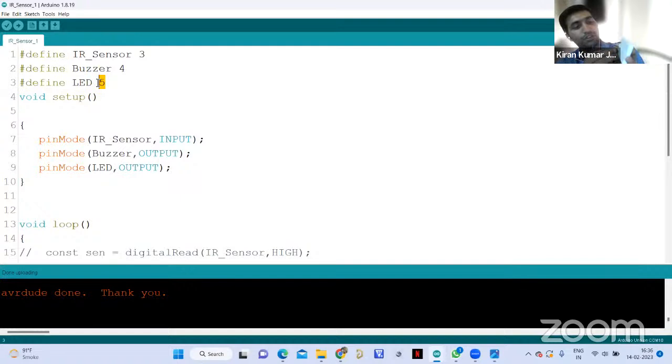Connection is quite simple. I have taken the IR sensor's output pin to pin number 3. So I have connected pin number 3 over here, the digital pin of the Arduino Uno. The rest is quite simple itself, so let me connect that.